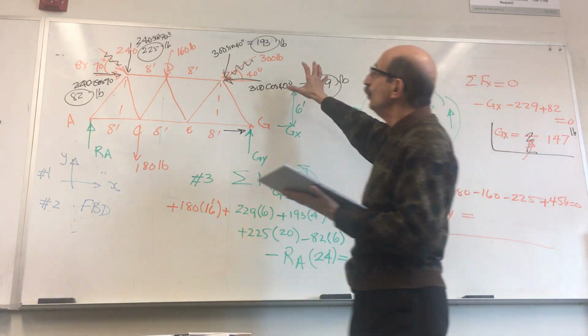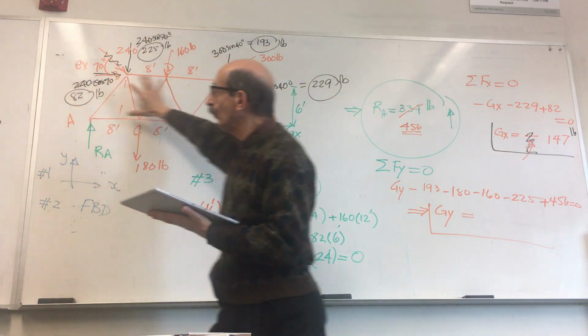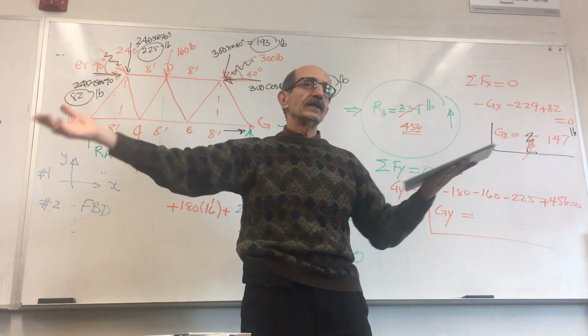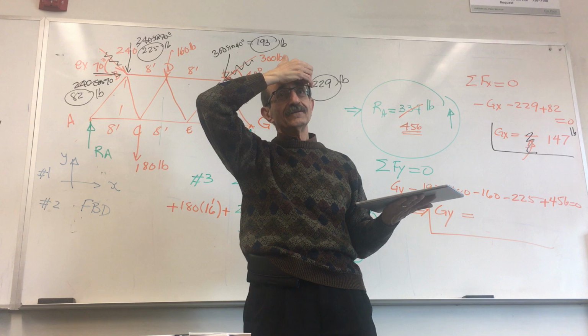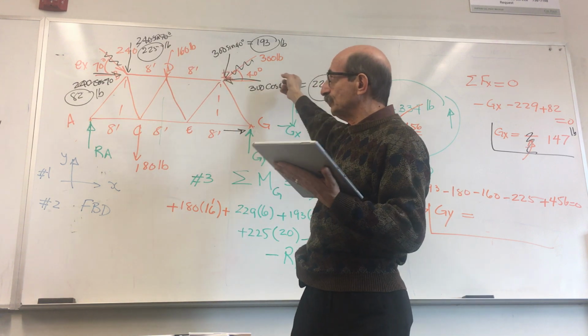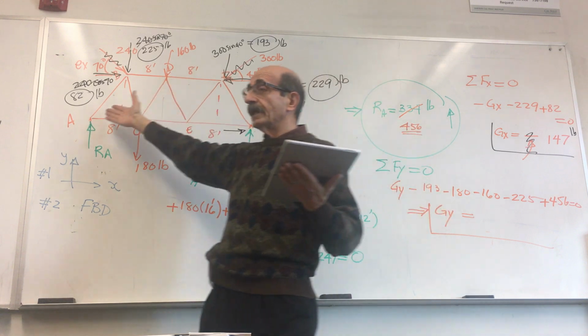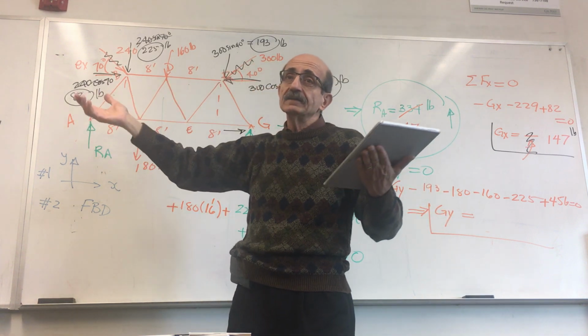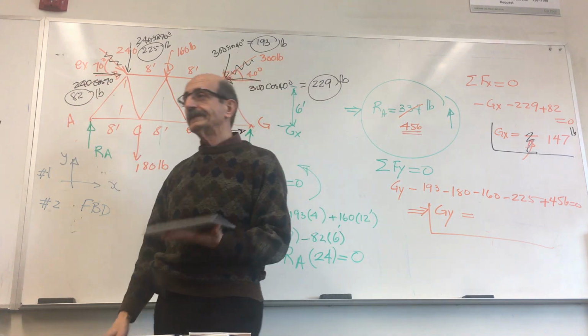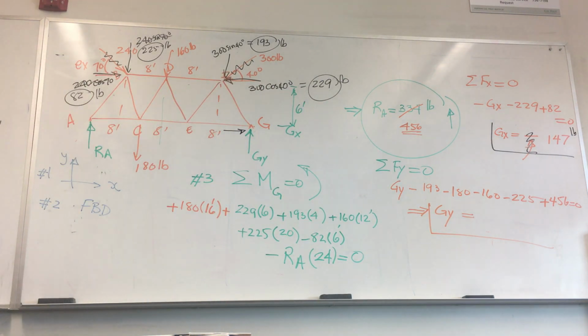It's only asking you to replace all these applied forces with a single force. And you know how to do it, right? Yeah. Replace all of them with a resultant, put it, say, at point A, and the summation of the moments of those forces at point A, put it there. Okay, so I was hoping that you still have 3 minutes.